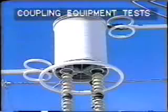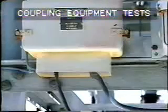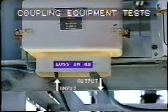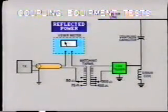In addition to test and setup of carrier equipment, the line coupling equipment must also be checked out and adjusted as necessary. We talked about this briefly in earlier segments of this tape. In general, the tests will include measurement of line trap impedance at different frequencies, insertion loss in dB between input and output of the line tuning equipment, reflection loss using a dummy load at the tuner output, reflected power measurement with transmitter and receiver in service.